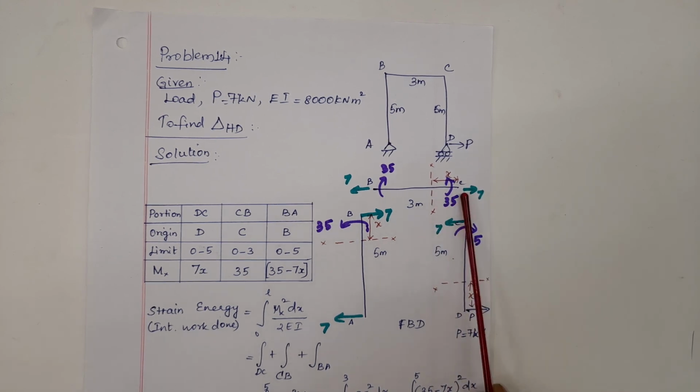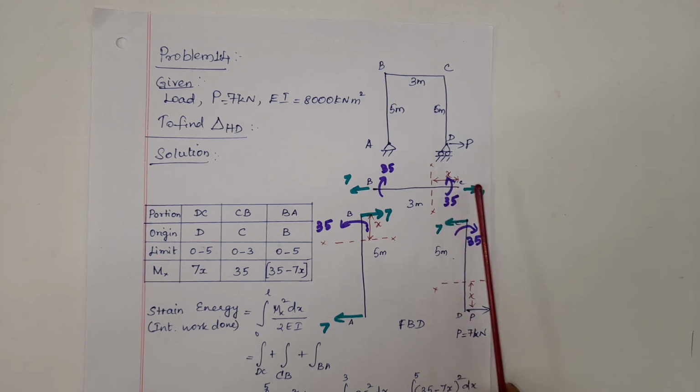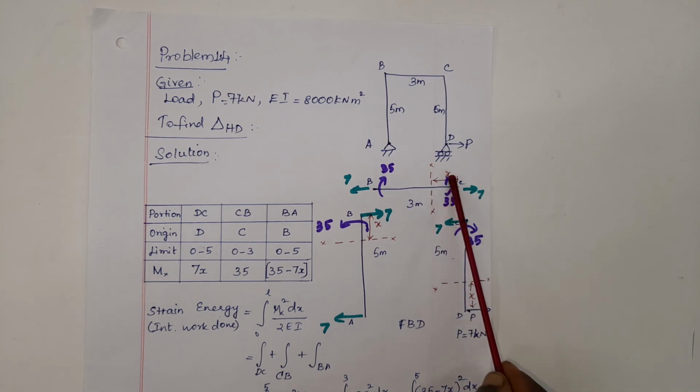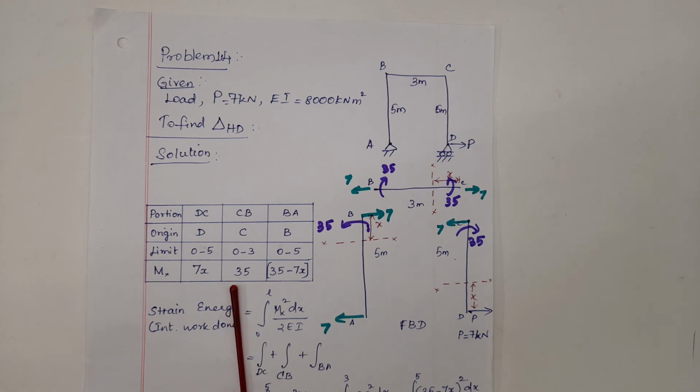So here at C there is an axial reaction that doesn't give rise to any moment about the section. There is already a moment of 35 kilonewton meter acting in the anti-clockwise direction. This causes a moment which pushes the beam down if it goes towards a section. It is taken as sagging bending moment or positive bending moment. So I write here plus 35.